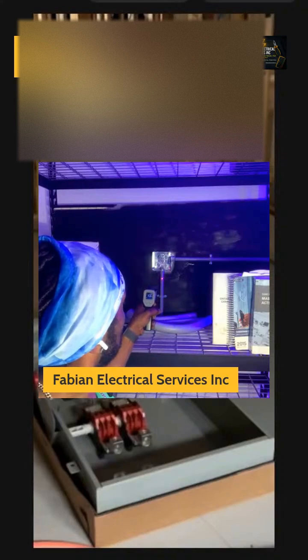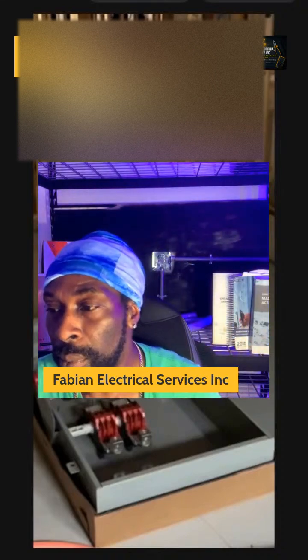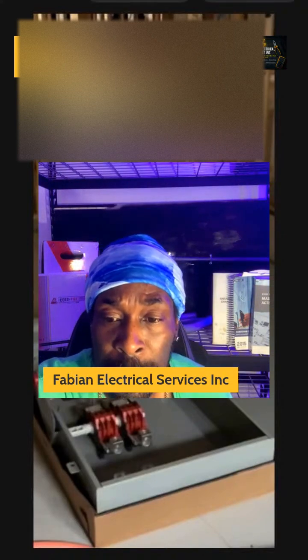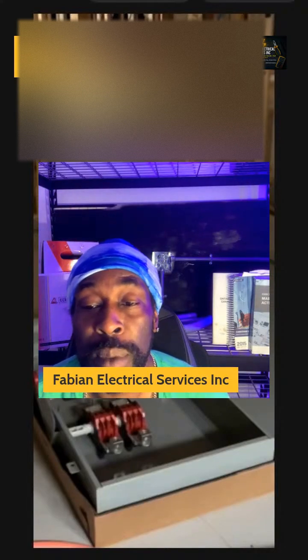Same thing here. So again, PVC expands. PVC expands at a rate of 0.052 millimeters per meter per degree Celsius.